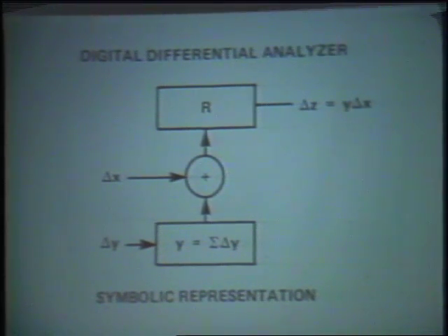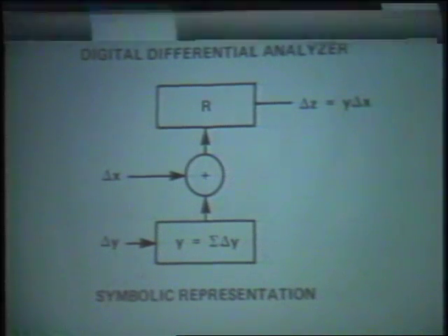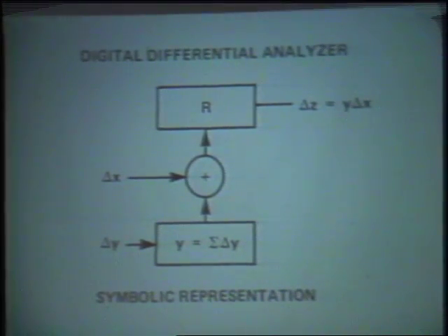With each increment of y, each pulse gets added into this register, which is equivalent to the integration for the variable y. And then each time an increment of x comes, y is added to r here, and as is obvious, if you continue adding it to it, you'll get overflows from this register, and those overflows, increments, are proportional to y delta x. So in effect, this is a multiplication, and the lower part is an integration.